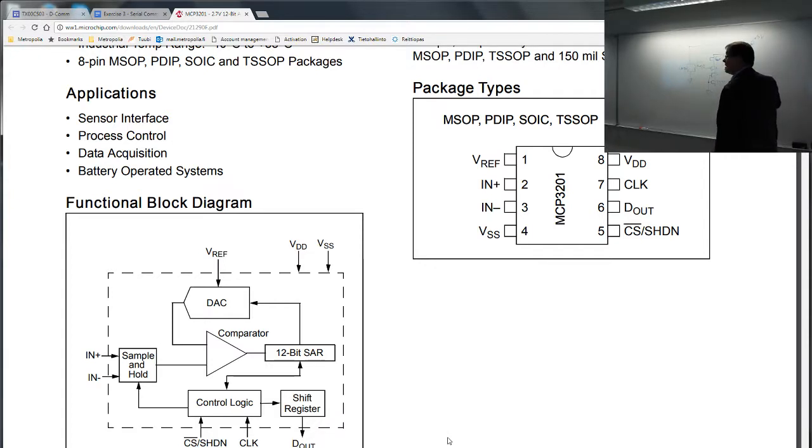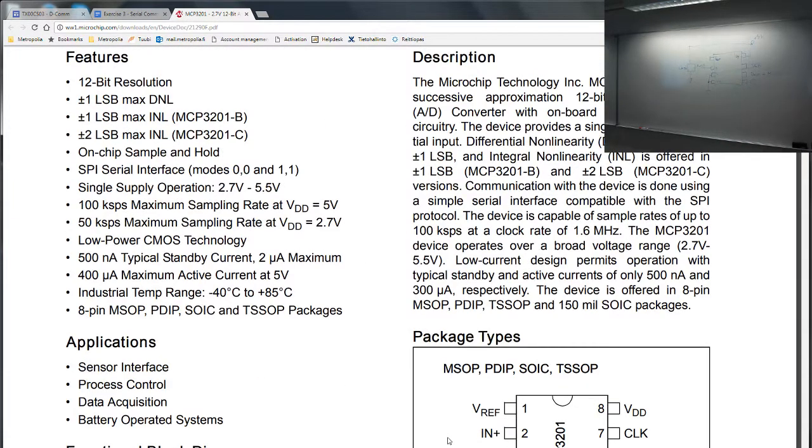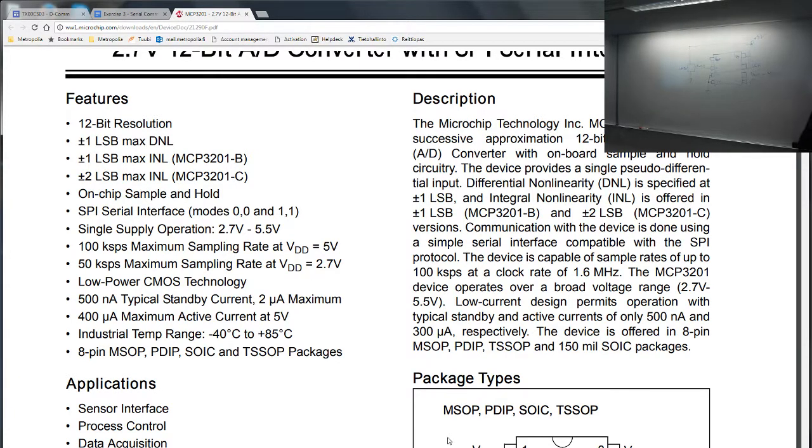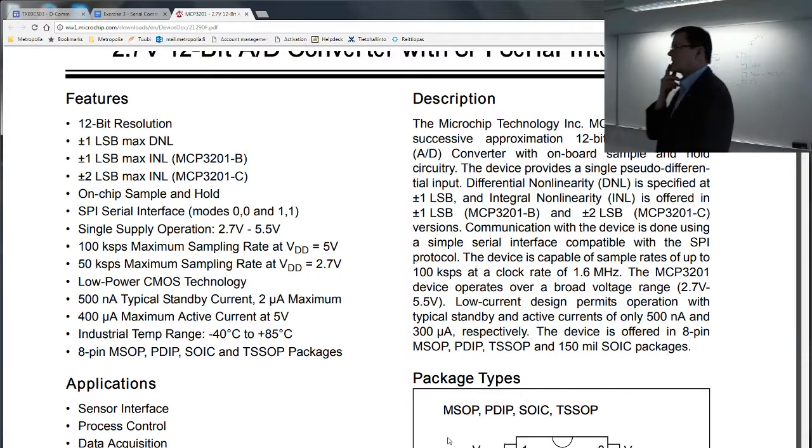Yeah, and then there are these SPI signals. Chip select, the digital out signal, which is actually master in slave out, and the serial clock. I think on SPI it was SCK. Okay, so those are the connections. Then you need to check out how fast this can go. This is pretty fast, actually. You can run it, I think, up to 8 megabits per second transmission.